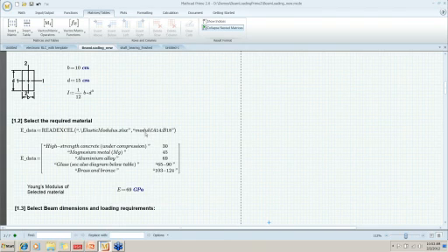So there's a worksheet tab called Moduli. So we use the standard Excel notation, the sheet name followed by the exclamation point, and then the starting and the ending data cells. So we're reading in the data. We're assigning it to a variable called eData. Okay, and we're looking at it a little bit here.